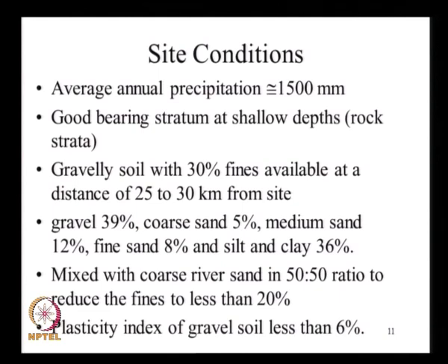So, it is very important that we use a soil that has very good compaction properties, and at the same time it is not compressible in future. So, that is one reason why the fly ash or the pond ash could not have been used at this site, because it is not possible to compact the soil to very high heights.